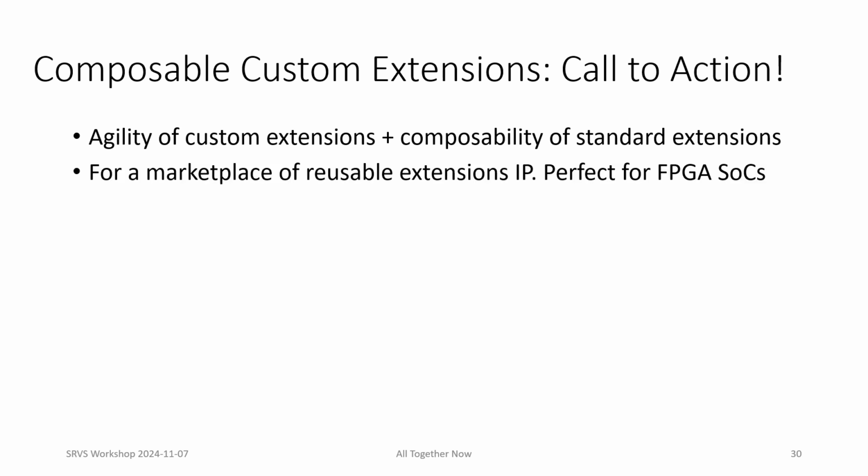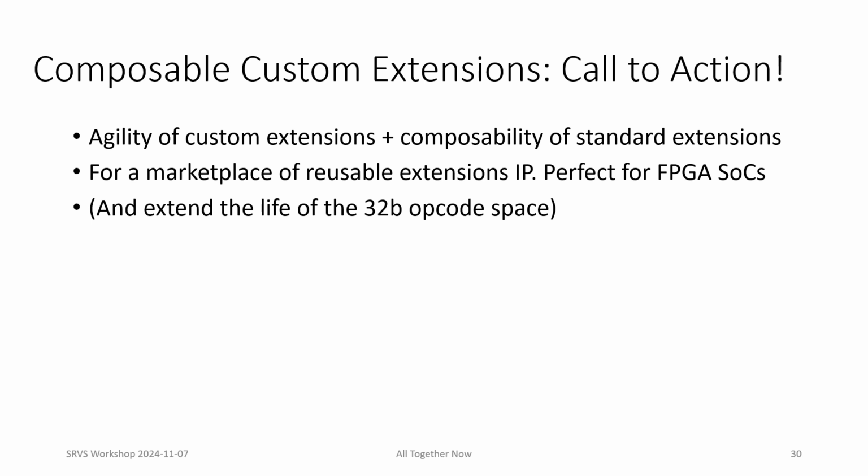And this will bring a marketplace of reusable extensions IP so that new SoCs can pick from a catalog of accelerated hardware and software solutions, which is perfect for FPGA SoCs. And just imagine never having to re-implement yet another packed SIMD reduced precision 8-bit floating point unit because you can just reuse a perfectly good one that already plugs into your RISC-V core using the industry's standardized extension logic interface. Composable extensions can also extend the useful life of the 32-bit RISC-V opcode space.